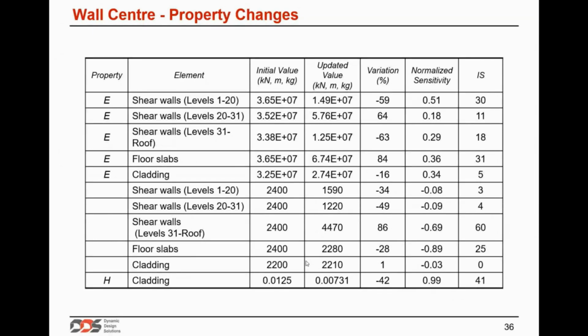What is the stiffness to be estimated for every location of that beam is really a matter of estimation of equivalent properties, so it is not unusual to have large modifications needed, because these are not true physical material properties but more like equivalent properties. So the elastic modulus is more like a stiffness indicator rather than a material property.